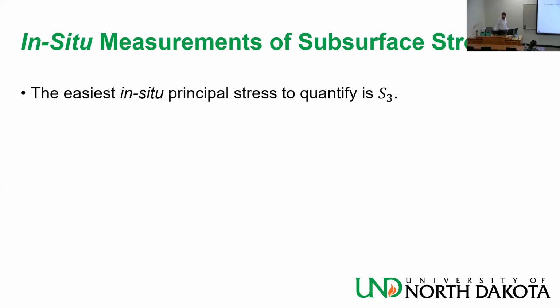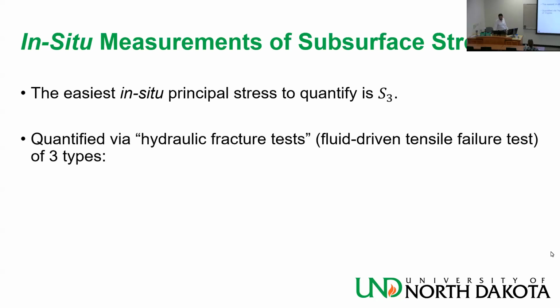So how do we measure those stresses? The easiest to measure is S3 because it's the smallest one. As we learned later in the module, when you have a tensile fracture, it opens against S3. So if I try to make a tensile fracture, I open against S3. If I do a leak-off test in my well, that's what I'm ultimately trying to do: get to the point where I'm just about to open this tensile fracture. So I'm trying to beat this S3.